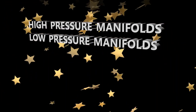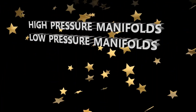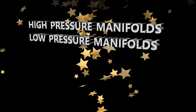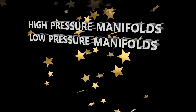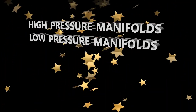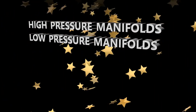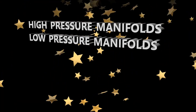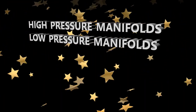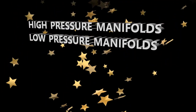Okay, so on the pressure relief valve, there is a predetermined value. Basically, if the pressure gets to be too high, and what's considered too high is going to be 237 bar, or the equivalent, 3,436 psi, that's when it'll open. And then when the pressure starts to go down, lower and lower, at what point is it going to close? Well, that point is at 220 bar, and that's 3,190 psi. All right. Okay, so then you also have, of course, HP filters.